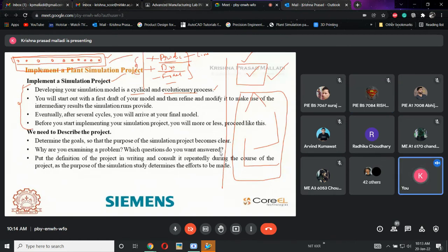Can these two differ, or will they be the same? For example, suppose machine 2 is required even after machine 3. In product layout, we will have a straight line, but for process layout, we will have to go back to machine 2 and then continue with the process. So is a process layout an efficient one or a failure? It depends on the situation. Okay, fine, I agree with your answer.